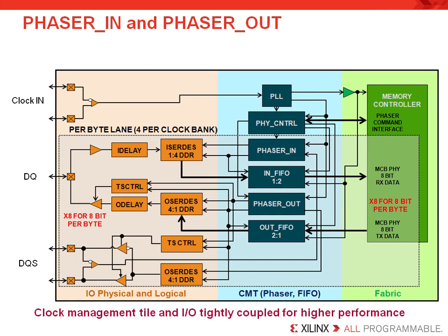Now, on the left of this diagram is the conventional I/O interface using the IOB resources. We can see that the DQ is a tri-state implementation, as we would expect. The DQS is a bidirectional differential signal. Now, we have the SerDes logic dedicated in each of the IOBs for just this kind of situation. The middle layer in blue is all in the clock management tile resources.